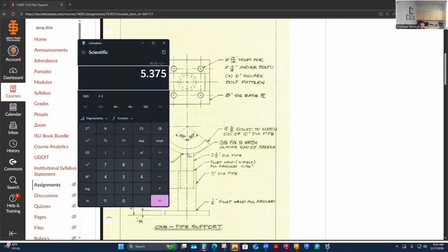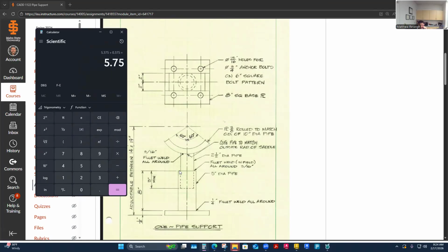And then I have a 3/8 plate thickness. So I can say here plus 0.375. So really I have fixed dimensions here, 8.5, and then a fixed dimension here to there as 5 and 3/4. And what's the difference after I take those two off? I'm thinking of the longest height, 19 inches. What I'm able to figure out would be the dimension from here to here. And then I just have to add the 3 inches to my part.